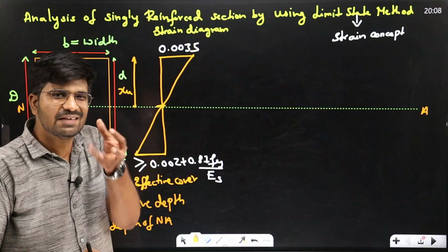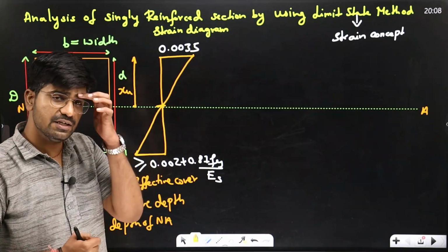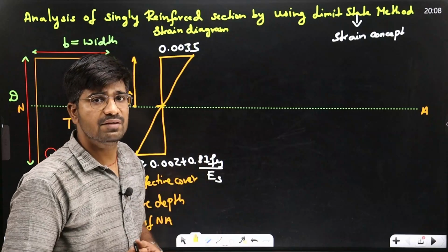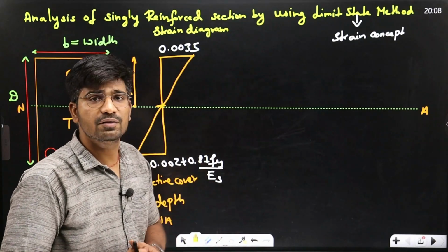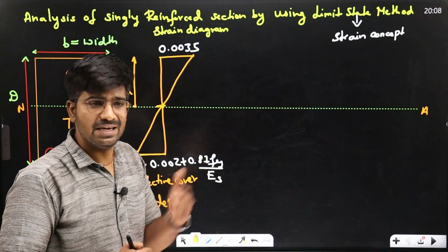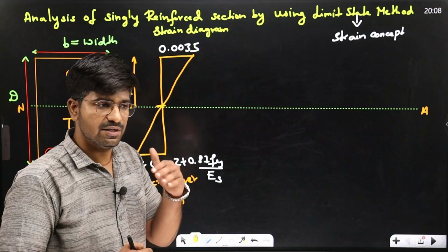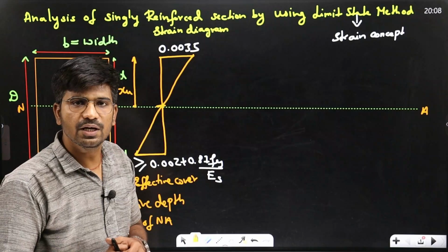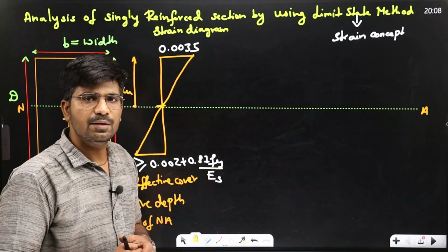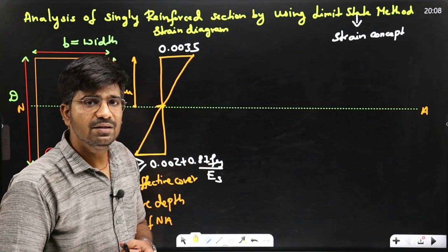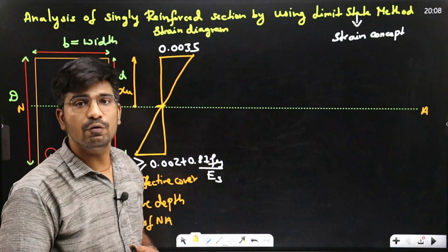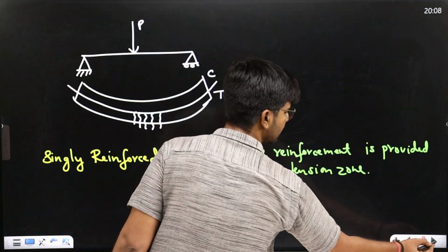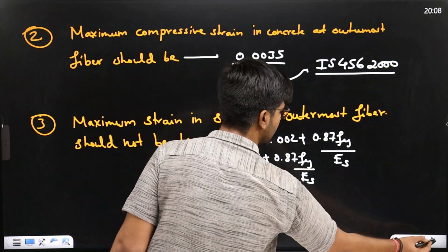Practically, a little bit of tensile strength is there. You have already studied in the properties of concrete different strengths like characteristic compressive strength, modulus of rupture, bending strength, then direct tensile strength and indirect tensile strength. There you studied that. But while designing, in the assumptions, what did we do? We have neglected the tensile strength of concrete. This is what the fourth assumption is.